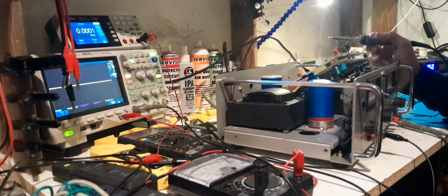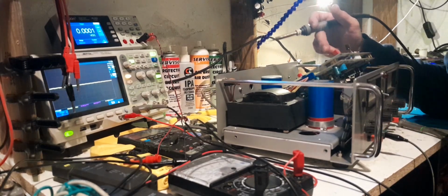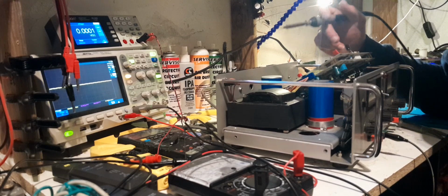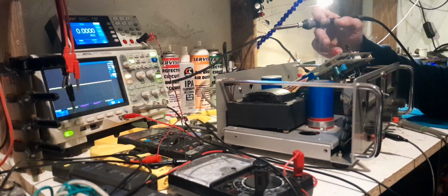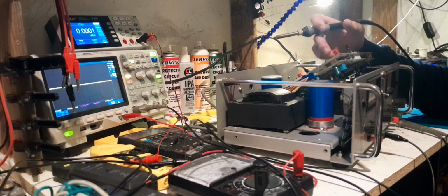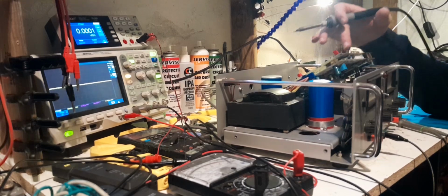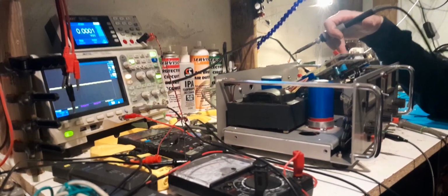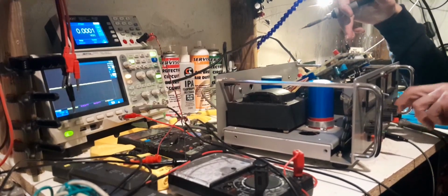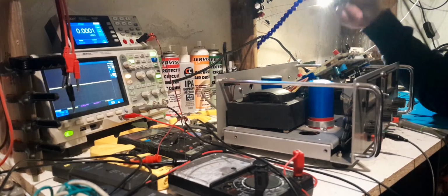Okay, so I think that's the one that sets, yeah, okay, the reference goes in one side of this op amp and the voltage set pot is on the other side of it, basically speaking, but they're interlaced in a way that I guess the voltage pot boosts up the output of the op amp so it amplifies the reference. That is then fed down here and compared to one of the inputs on the constant voltage monitoring op amp, and the other input's obviously looking at the output voltage. So that's how the constant voltage circuit's working. So there you go, finally traced something out for you.